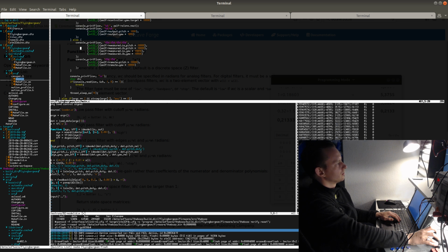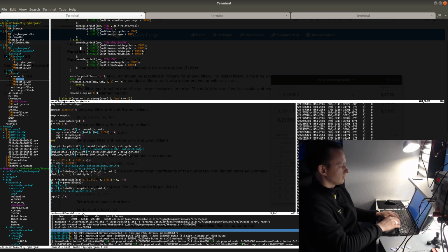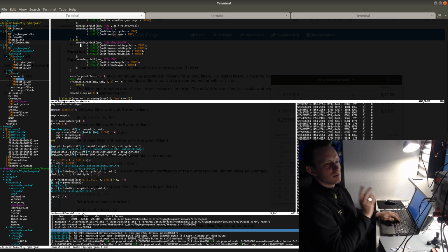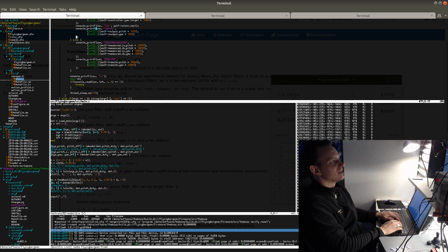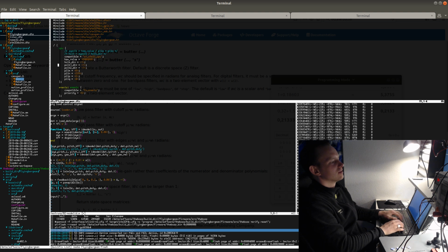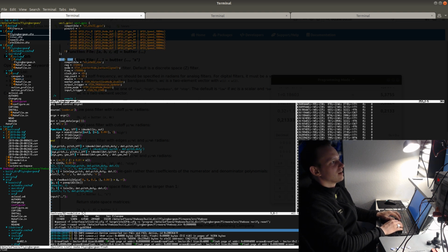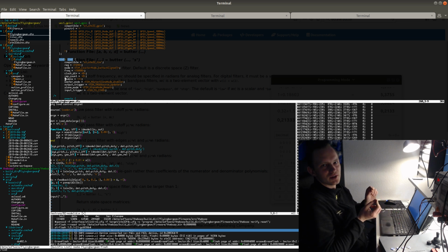This is really weird. So sometimes it seems that the values are correct, sometimes not. And I know why that is. I know why this is happening. Because I have updated my repetition counter on timer 8, and I set it to an even value, which means that sometimes it's going to measure on the high edge and sometimes on the low edge, because it's triggered by the update event.